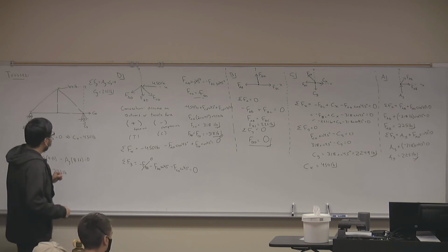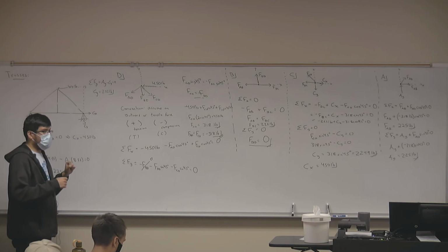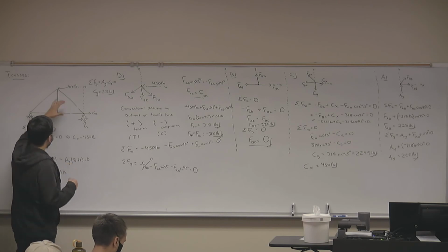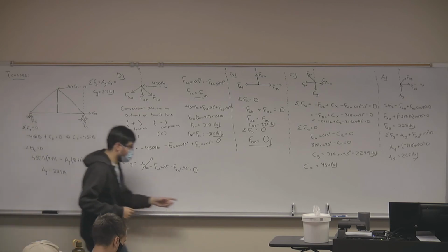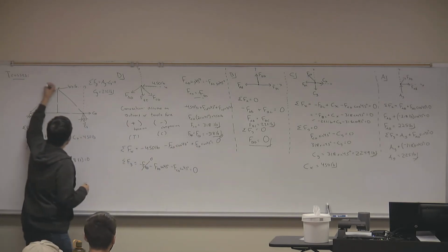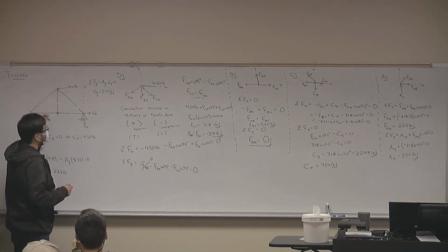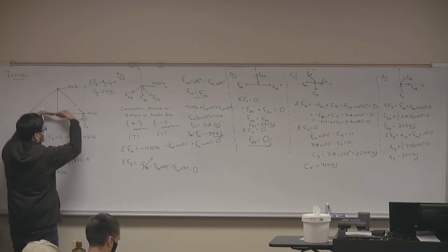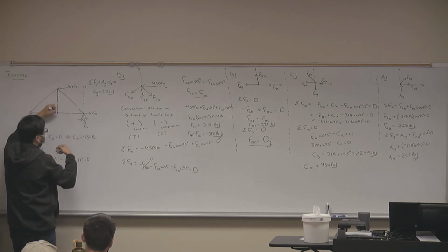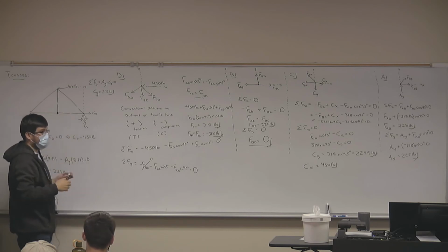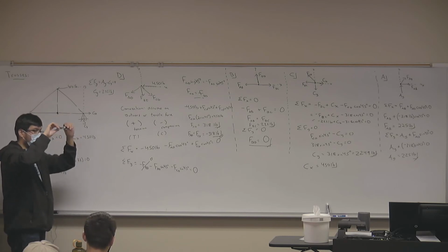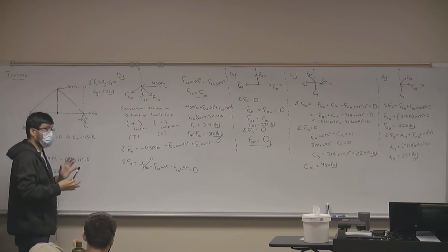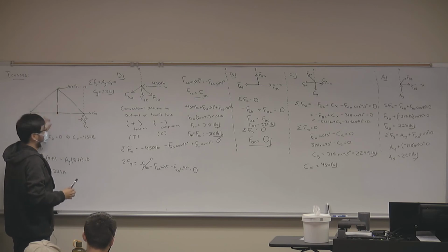Yeah. So these trusses are rigid bodies, right? Now, the way the trusses are arranged, their connections, their joints are taken to be like pins or hinges, right? Which means that they can freely rotate about the hinge or pin, but they cannot move linearly, okay? So what that means is that the joints will only experience either tension or compression. So those are the only two possible forces that these trusses can experience, okay?